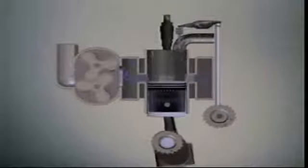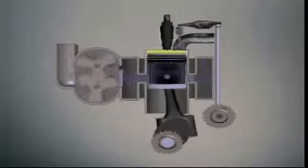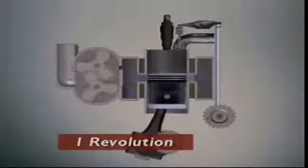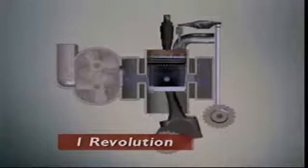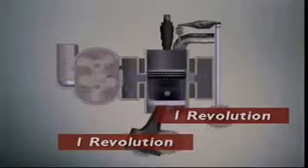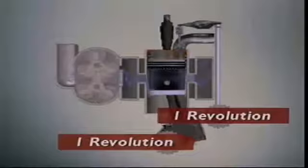This is a two-stroke diesel engine. How many revolutions does the crankshaft make in one cycle, from intake, compression, ignition, power to exhaust? It makes 1 revolution. During that revolution, the valve opens and closes once. The camshaft makes 1 revolution too. Camshaft and crankshaft must rotate at the same speed. The gears must be the same size.